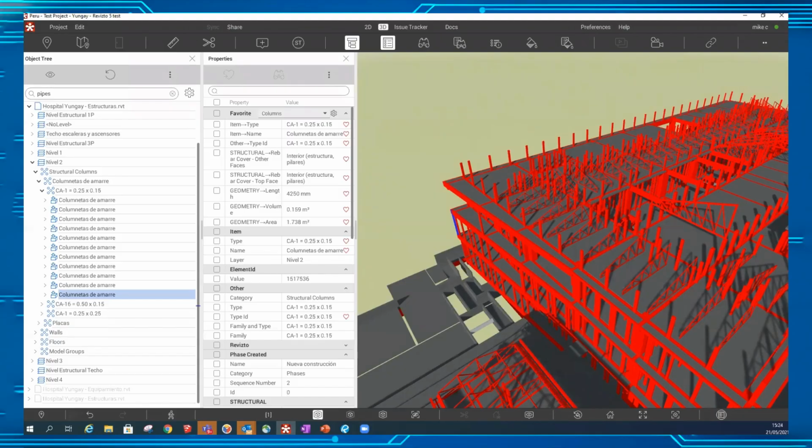I think if you want a timeline that you can slide forwards and backwards to see where things were at a particular time, then you'd probably do that in something other than this, probably Navis. But if what you're trying to do is record at a point in time what stage things are at, then you could do it in the way that I just described.